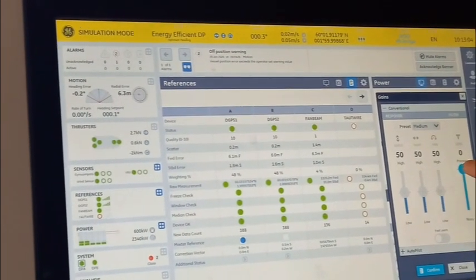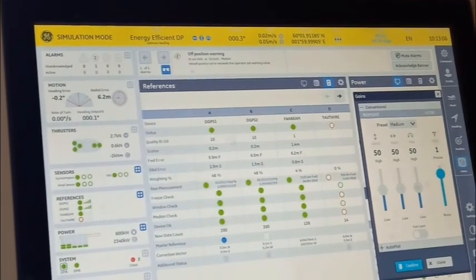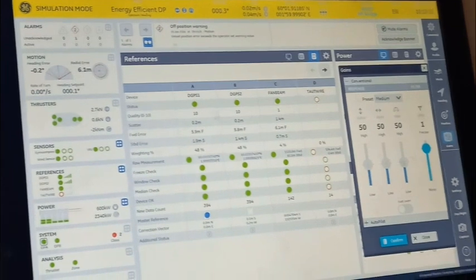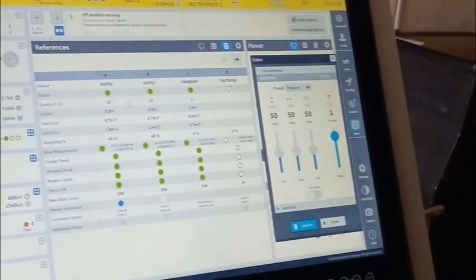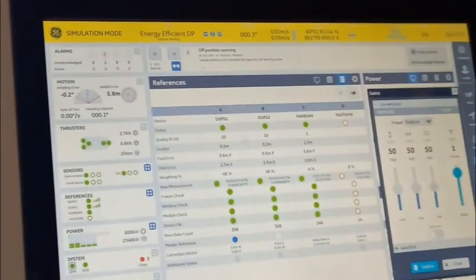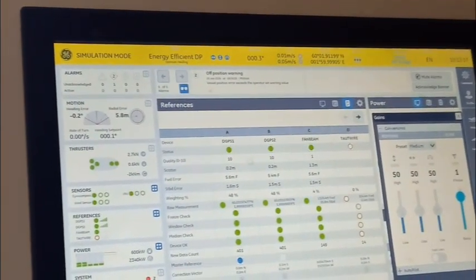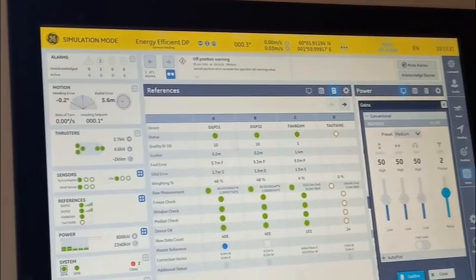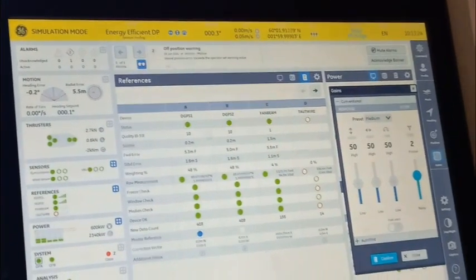I'm telling you, if you are having acoustic, because normally the acoustic beacon will send position data back every 2 seconds, you need to reduce the level of the filter to adapt to that low frequency signal telegraph.